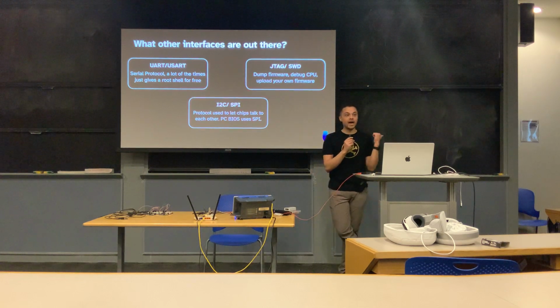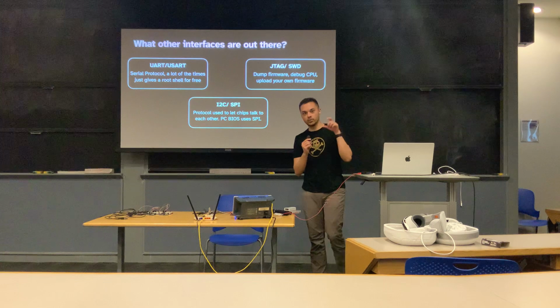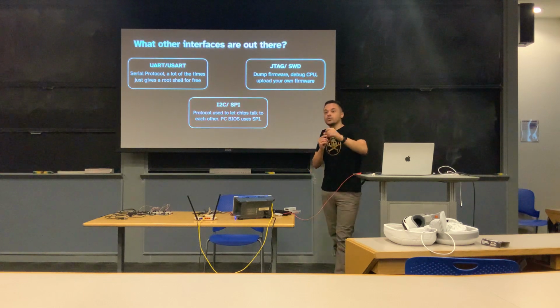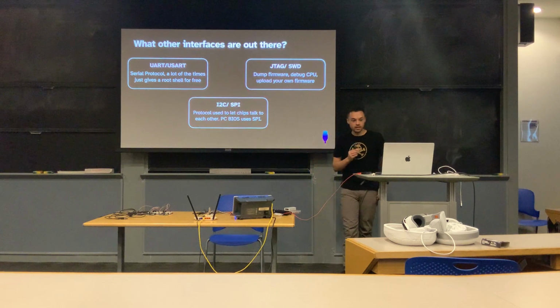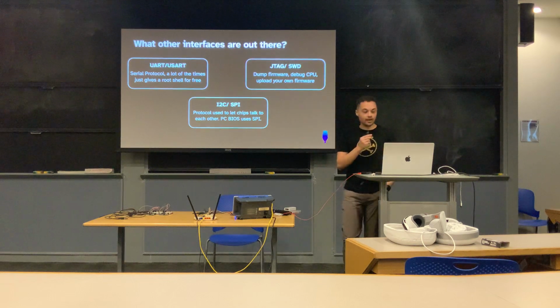We got a PC in the lab that we actually attached a debugger to, and we were able to dump the SPI flash from the BIOS and reflash it and modify it with our own BIOS image. And so you can do kind of crazy things like that with SPI.